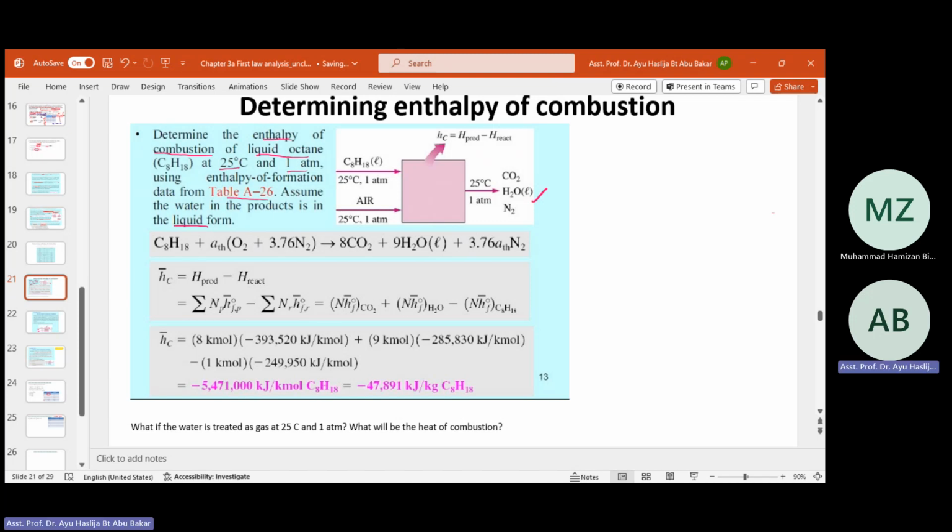First step, okay, in this question, sebenarnya dia tak ada bagi equation ni pun. So first step, you need to generate the combustion equation. Liquid octane, C8H18. So this one is the common combustion equation. Mole of CO2, which is X. H2O, which is the Y over 2.